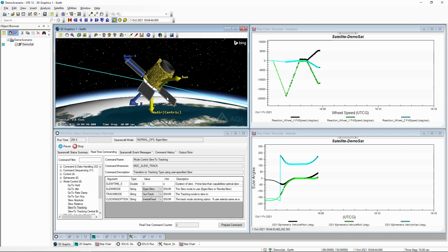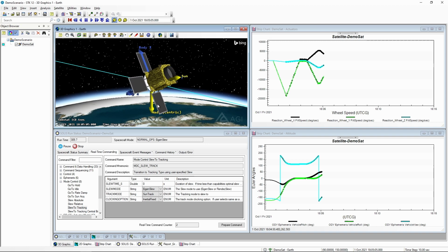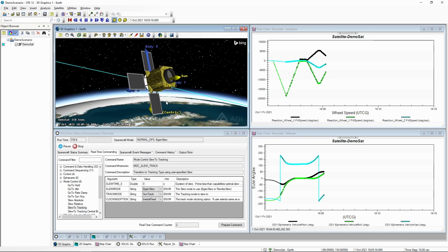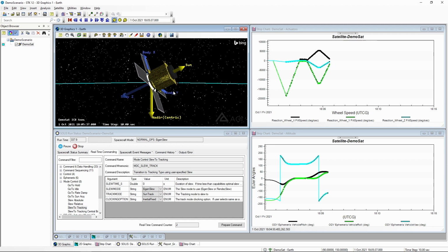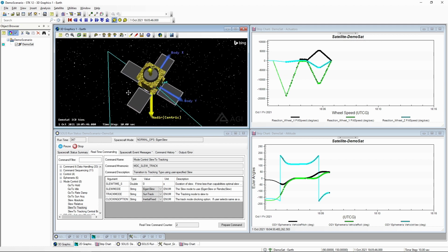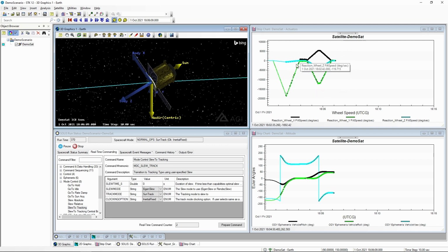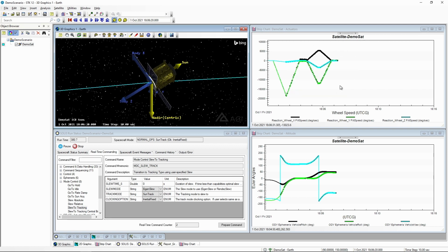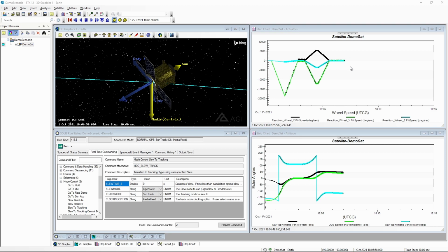We are issuing these commands to max flight software, which is executing a real control algorithm that would execute on a spacecraft, and Odyssey that is running within max is simulating the 6 degree of freedom dynamics models to propagate the attitude based on the spacecraft mass and the reaction wheel speeds that are being commanded. At this point, we have a completely configured attitude determination and control system along with the sensors and actuators that go into that system. Now we'll turn our attention to the power modeling.